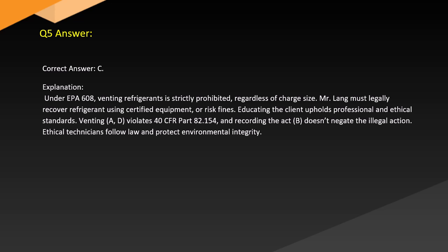Answer. Correct answer: C. Explanation. Under EPA 608, venting refrigerants is strictly prohibited, regardless of charge size. Mr. Lang must legally recover refrigerant using certified equipment or risk fines. Educating the client upholds professional and ethical standards. Venting (A and D) violates 40 CFR Part 82.154, and recording the act (B) doesn't negate the illegal action. Ethical technicians follow the law and protect environmental integrity.